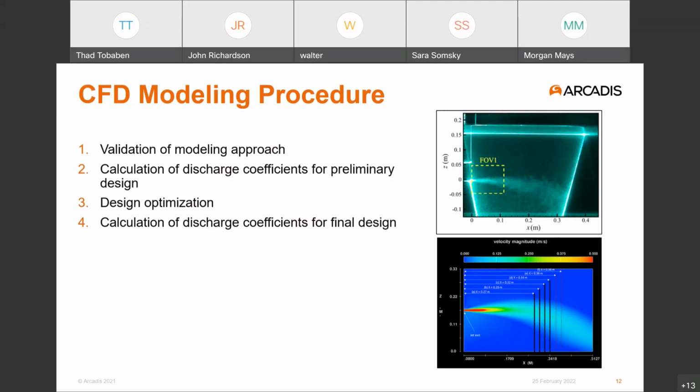The reason that this test case was chosen was that some of the other work that was done was meant to address what kind of currents in the lock would set up when the leveling system was operated. So an important aspect of answering those questions is being able to understand how the jet flows being issued by the exits from the leveling system would evolve inside the lock.